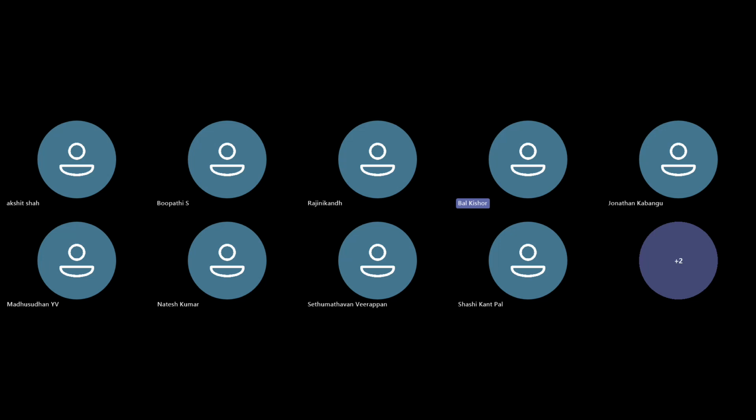Now, if you put your cursor on the wire, it will give you a pen type symbol. It is 5 volt which it gives you. Similar to that, what is the voltage here? That also it will give you. Maybe it will be less by 0.7 volt. So yes, it is 4.3 something. So by 0.7 volt, it has reduced.